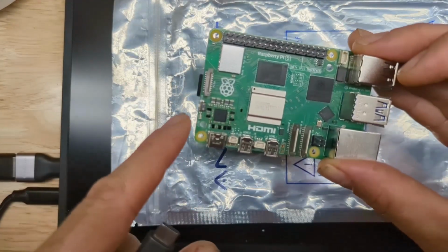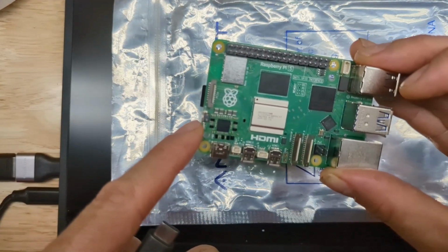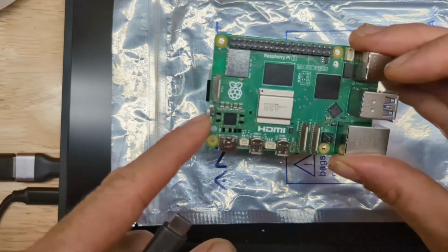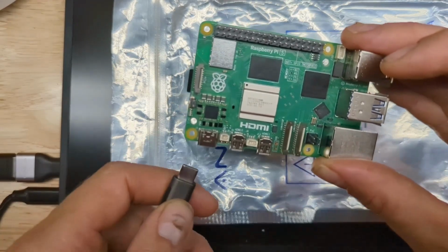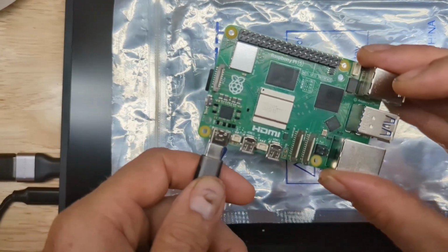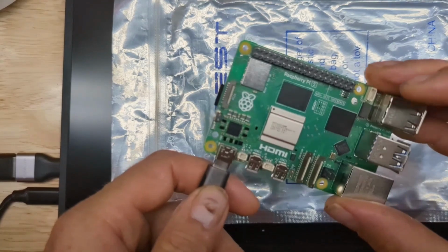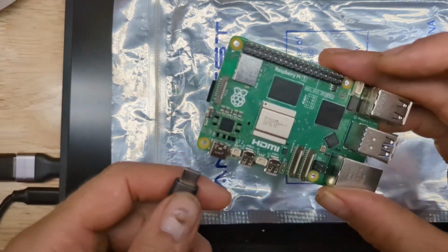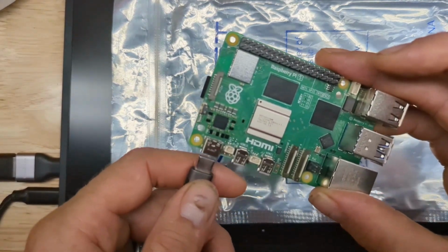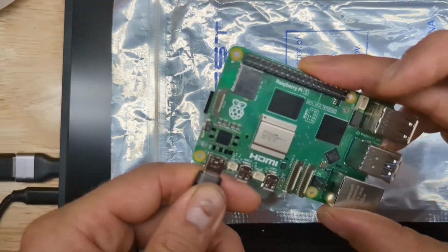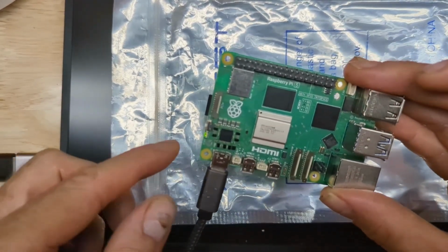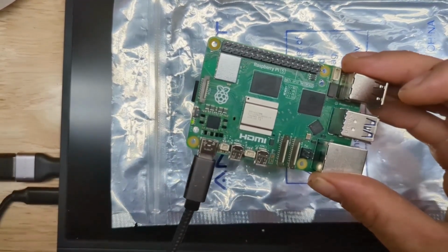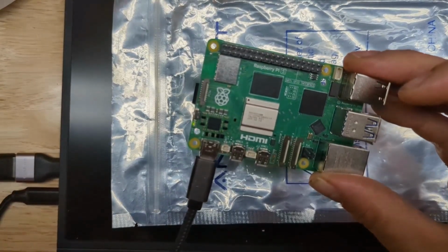Now, when we plug this thing up, one thing we're going to be looking for is this little LED. This will flash red when it first boots, and then it will go green. And then after a few seconds, you should start seeing the green light flash. As long as you see that, you know the device is booting up correctly. If you get a red-green flash alternating, then you've got a problem and need to troubleshoot further. But for the most part, as long as you wrote the image and didn't get any error messages, you should not have any problems with this boot process.